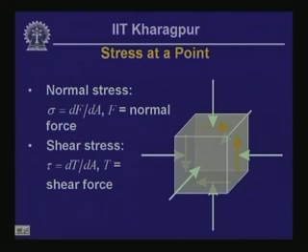shear stresses. So, we are beginning here with the shear stresses acting on the vertical plane on the right side of this particular element, and if you have got that kind of shear stress, in order to maintain equilibrium of this particular element, we are also going to have shear stress arising on horizontal planes at the top and bottom of the element, acting in clockwise direction in an opposite sense to the shear stresses that were operating on the corresponding vertical planes.